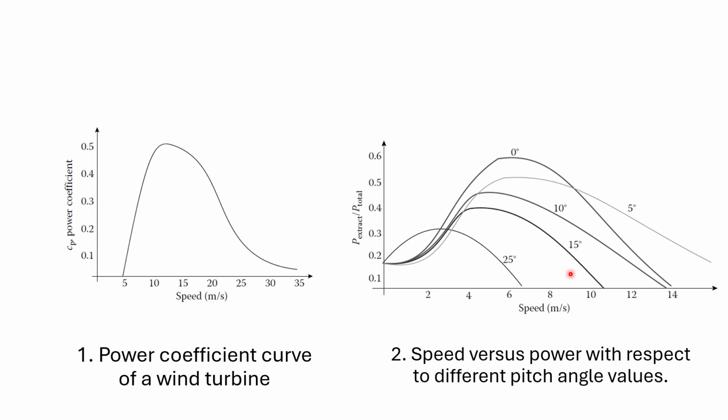In addition, the power coefficient depends on the pitch angle, which is defined as the angle between the blade surface and the plane of the wind rotor, which is shown here. This angle represents that. There is a great difference between onshore and offshore wind turbine power coefficients. For onshore turbines, the blades are designed such that the optimal tip speed is limited to roughly 50 to 70 meters per second, because the blade tips cause excessive acoustical noise and can cause damage at higher speeds. On the other hand, noise does not play an important role in offshore turbines, and higher speeds lead to slightly higher optimal values of the power coefficient.